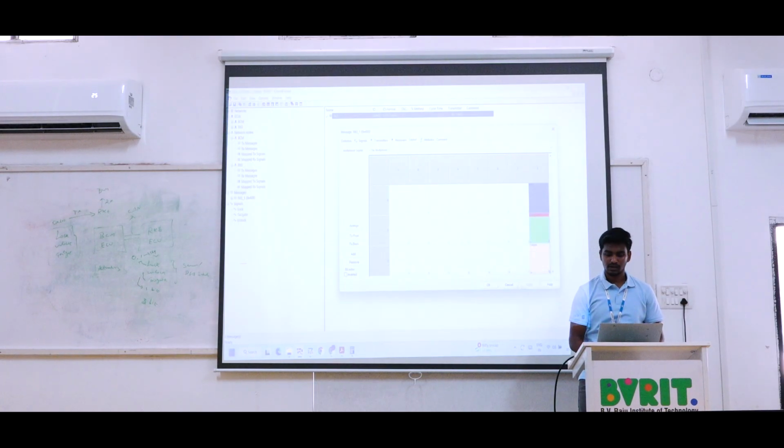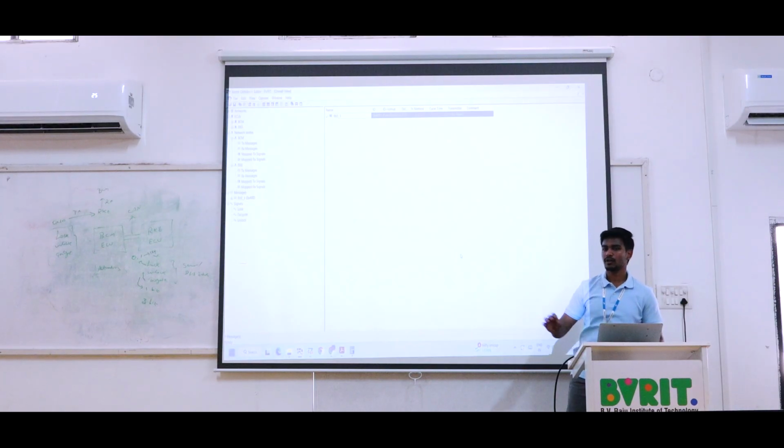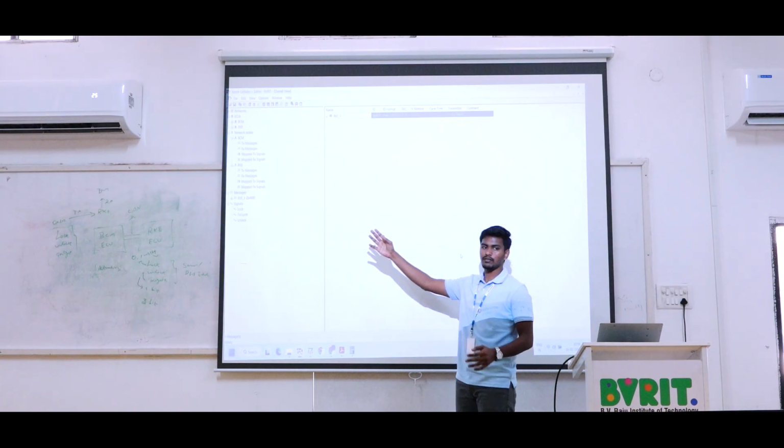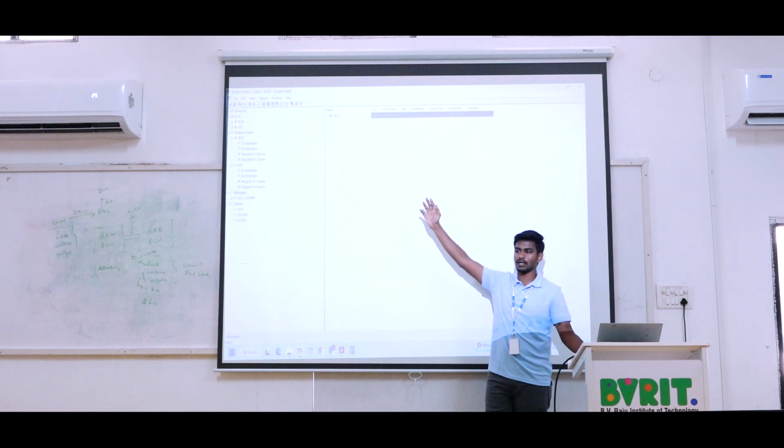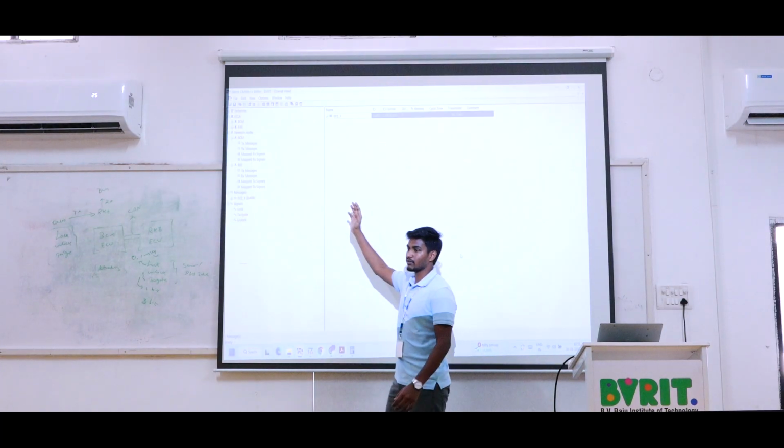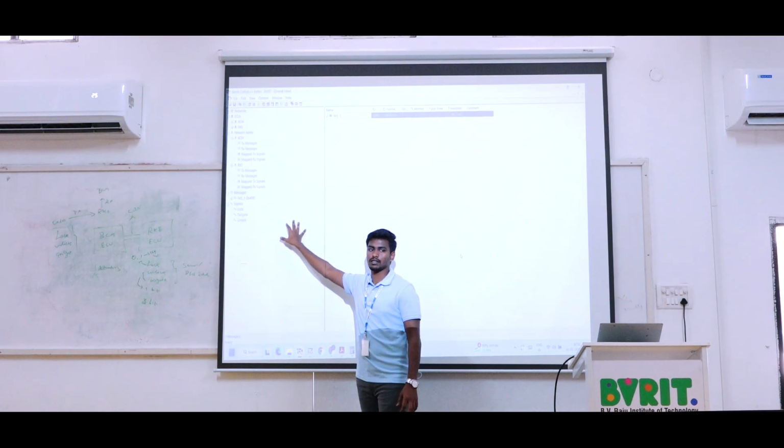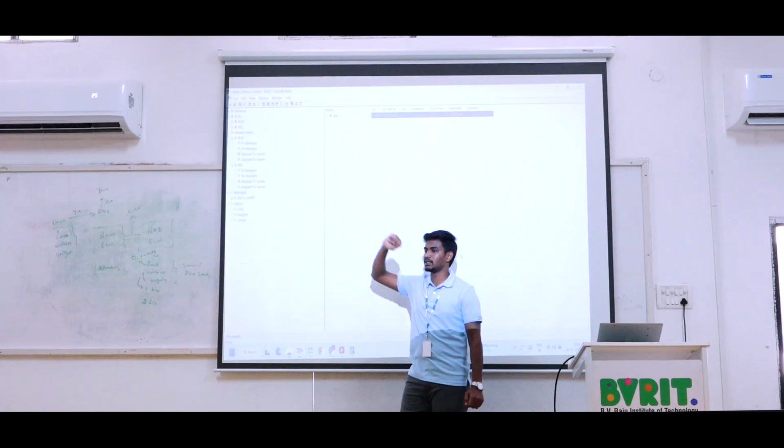Apply, and then give OK. So as of now we have created the signals and we have mapped them with the message ID of 400. In the 400 message we can get up to 8 DLC, but in the definition of 400 we created only 3 DLC.